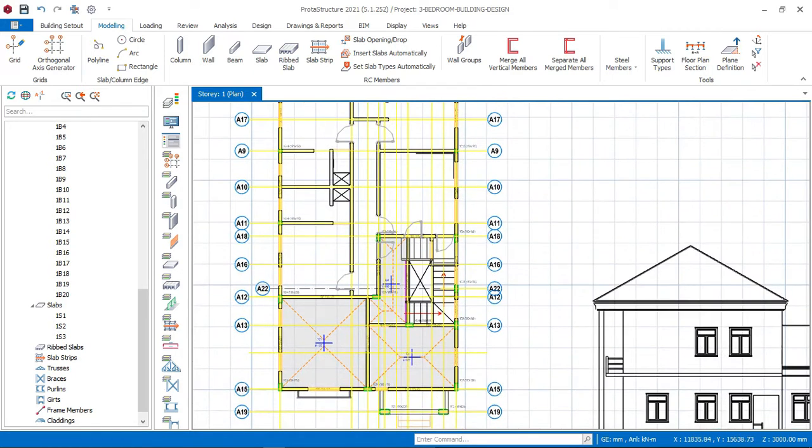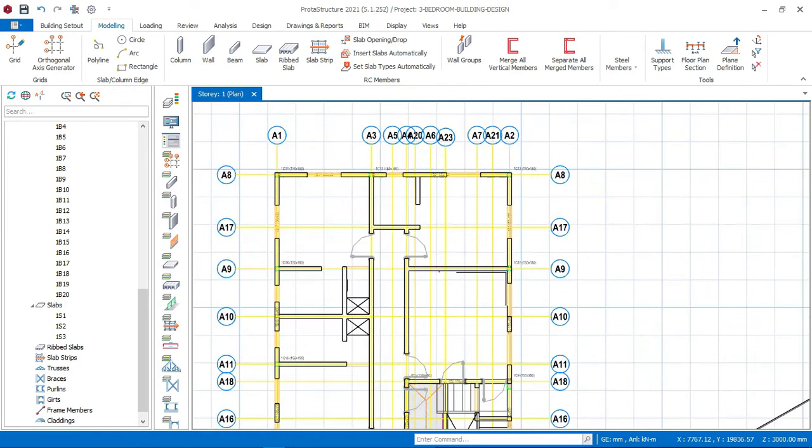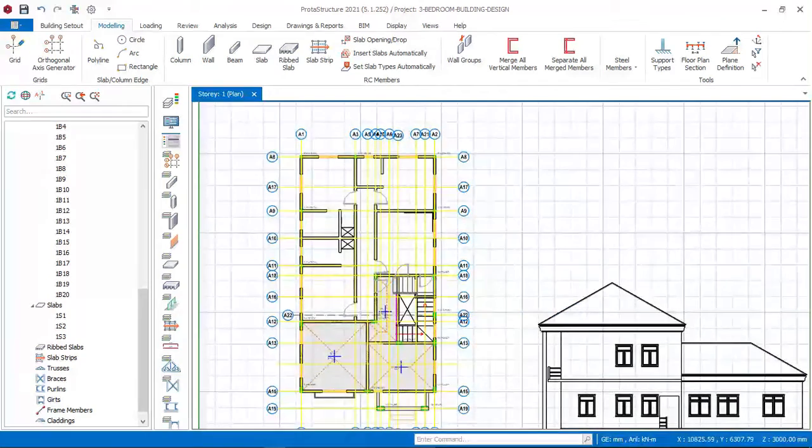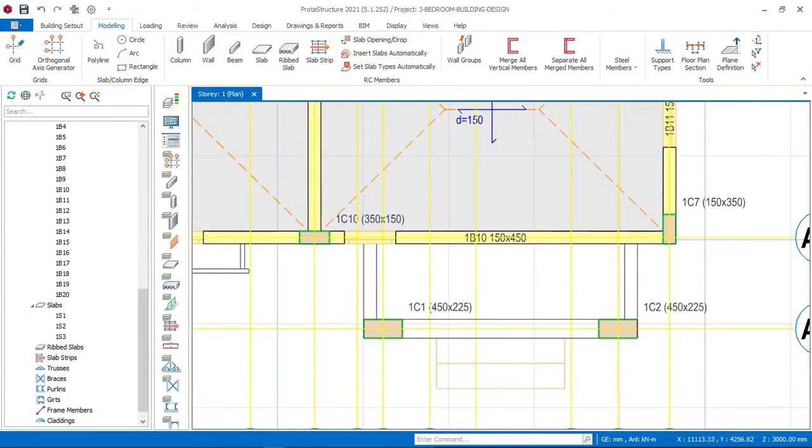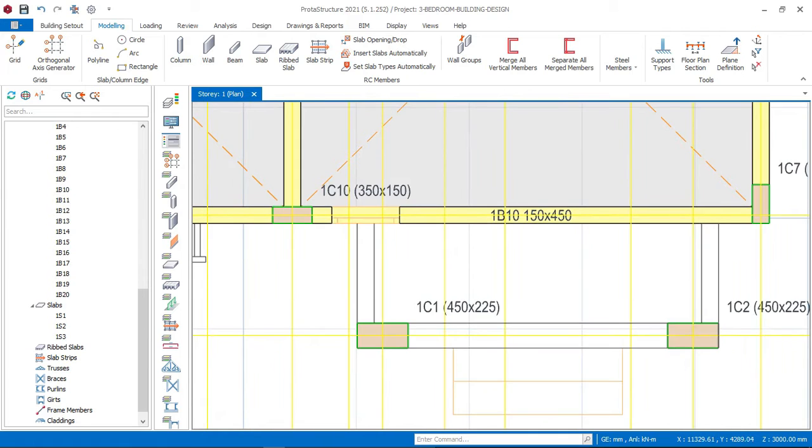So we will now go and begin to insert our hinge end condition. By doing this right now, since we have already done this, I will now have to go and offset this. So I'll click on this place because there is a beam here. We didn't offset that grid line.